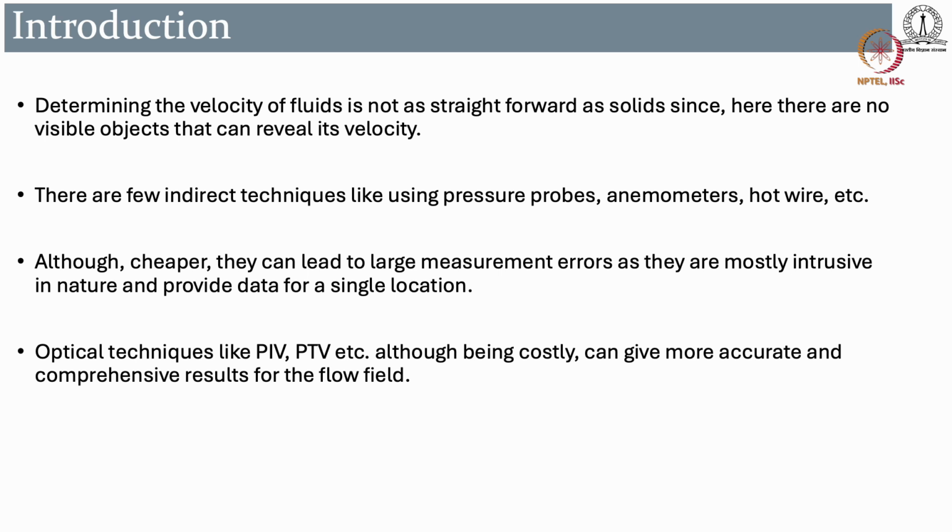Now optical techniques like what we are talking about, PIV and PTV, are very costly but can give you very accurate results, and they also give you a comprehensive result of the flow field. If you have a flow inside a channel, using an optical technique like the laser which I showed you initially, it illuminates the whole region from where you can extract data, unlike the other indirect techniques. And as said, these PIV and PTV techniques are mostly non-intrusive in nature, at least compared to the other techniques.